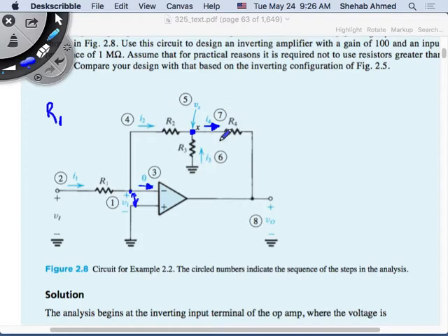A voltage drop across this resistor here, which was R2 in the previous case. Now we will find that the output voltage here depends on what? Fine, this is current flowing here. It will depend on this and the value of Vx. So I will have Vx, I will subtract this from it, and that's equal to V output.